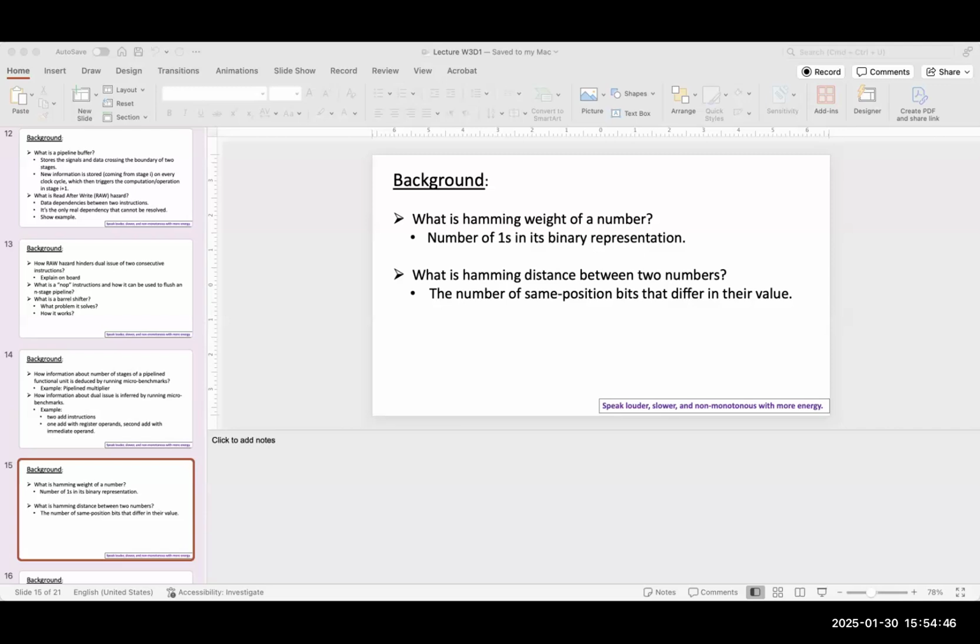On top of that, because they are able to complete 2 ALU instructions in one cycle, those which write back into the register, let's say here, right? If you are able to complete these two in a single cycle, it means you are able to write both R3 and R5 in the register file at the same time. So you have two input data lines, coming back from the last stage here into the register file. The register file, I'm assuming, is in the decode stage.